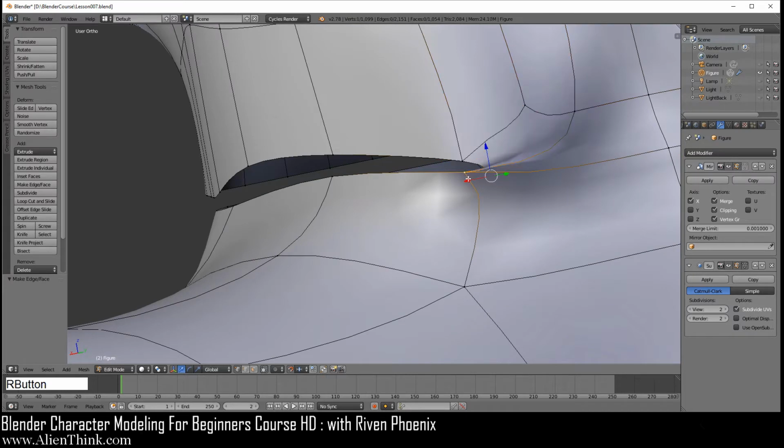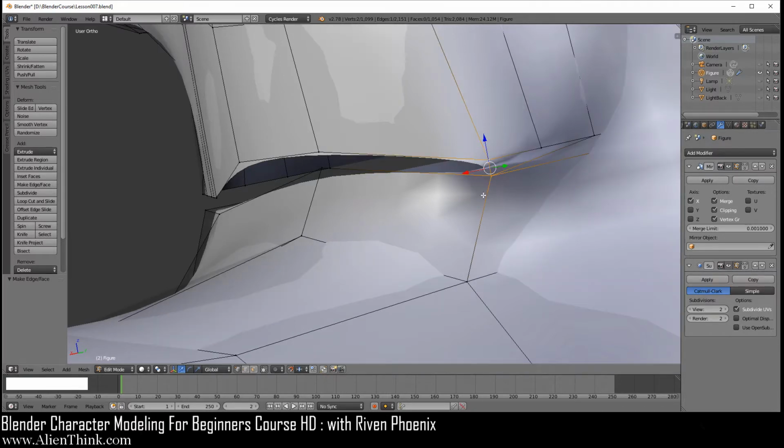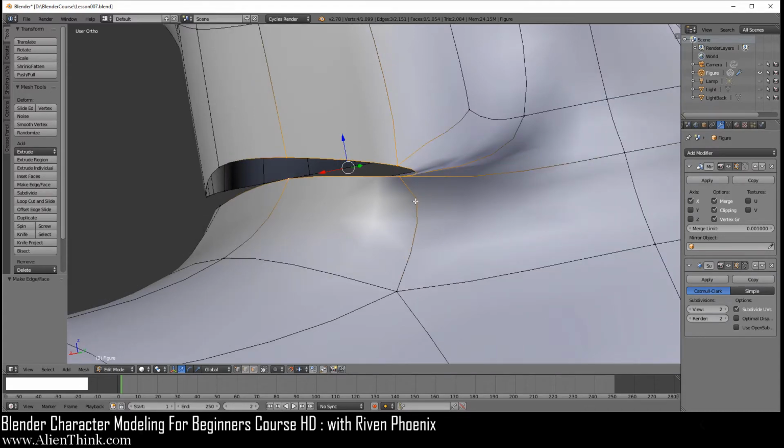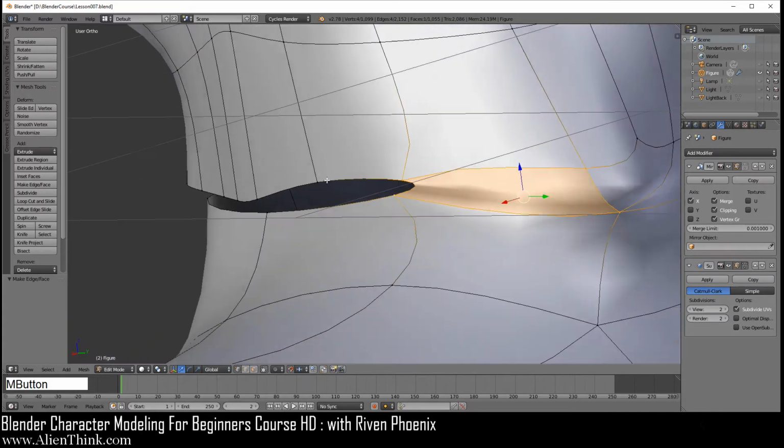So now you're going to get this vertex, this vertex. You can see that it's bending like this, right? It does that because it's just trying to show it to you this way, but you can always click this to see what's going on. You're simply selecting these 2 and you select these 2, right? But when you click on this, it looks a little confusing. Anyway, I'm going to click on F to connect these 2.